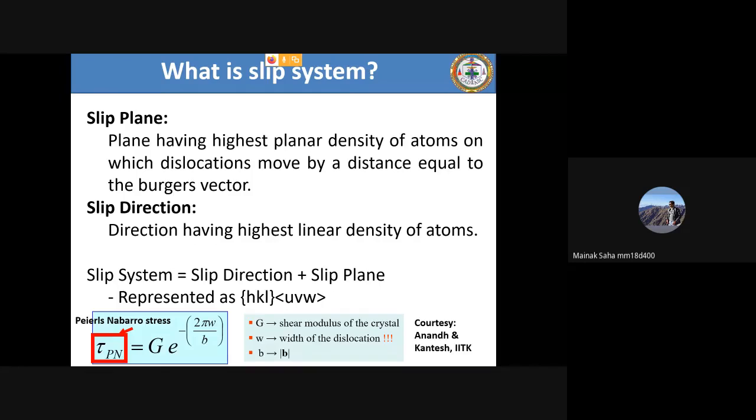Because if the continuity of the atomic plane is disturbed by a missing line, there is definitely going to be some localized strain in the material. When there is localized strain, the position of atoms in the particular plane is going to shift here and there. They will not shift randomly because this is a crystalline material, but definitely there will be some distortion.